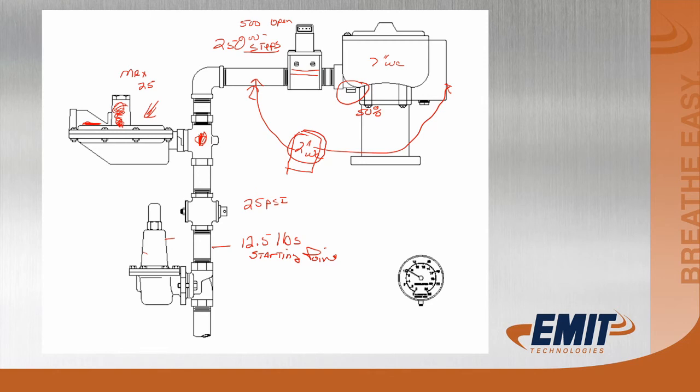Better to have too large of an orifice here for nice gentle fuel delivery than too small of an orifice and have this pressure set too high. It makes the carburetor very erratic.